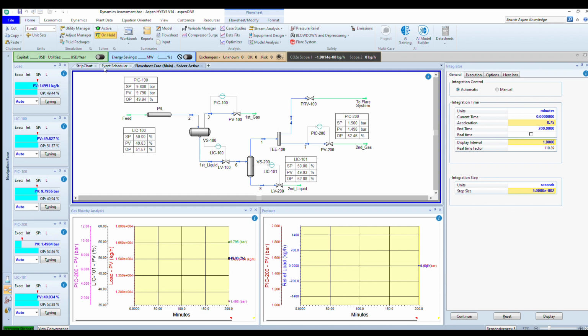In the event scheduler, the chronology has considered that at the time this valve goes fully open, this control valve will maloperate and will be considered failed. So this PV will be off. It will not function. At the same time, this level control valve is 100% opening.